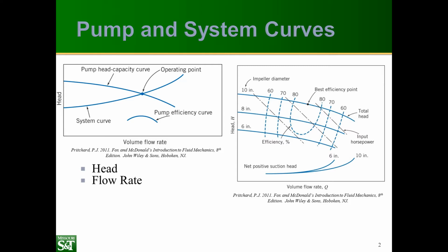Now, fully characterizing these pumps requires experimental measurements, but the ideal analysis techniques that we've used in this module help us to narrow our search. We could use the Euler turbomachine equation to estimate the rotor diameter or the blade angle that we're looking for. This means we could have fewer pumps to search through.